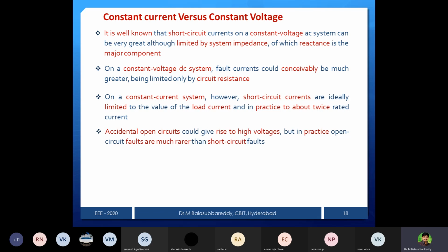In some cases if the feeder is very long, even on the distribution side, the last consumer at the end may get a larger drop, because a lot of non-linear loads are present in the previous taps. In that case voltage will drop down.